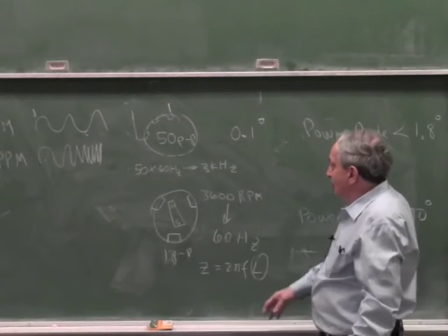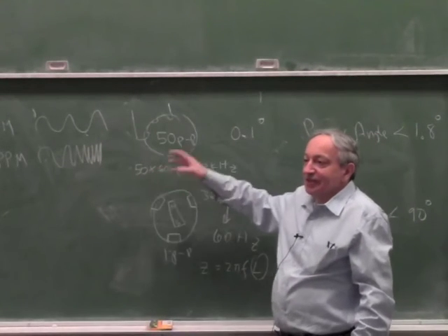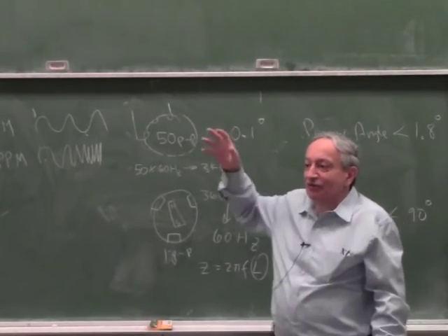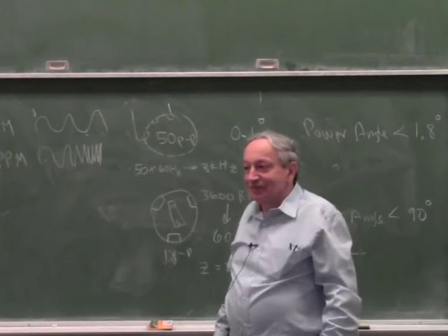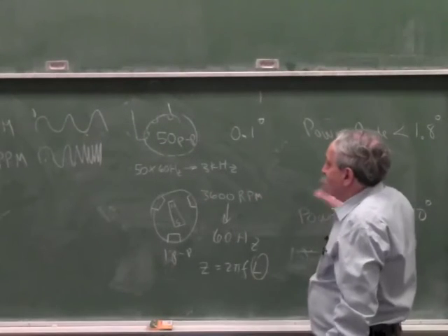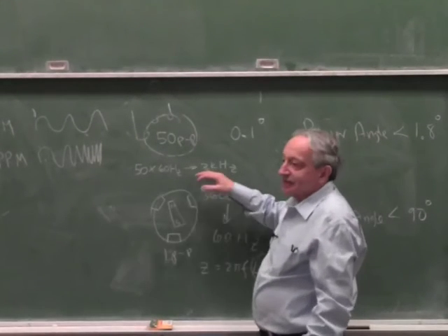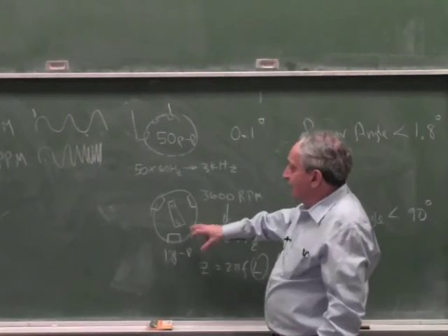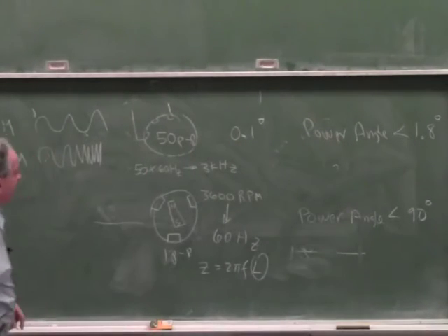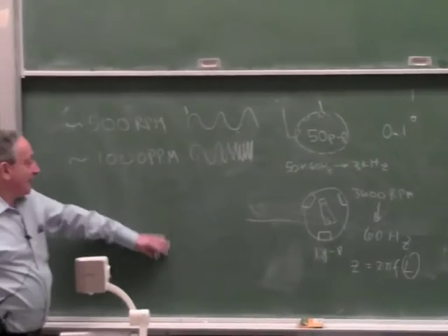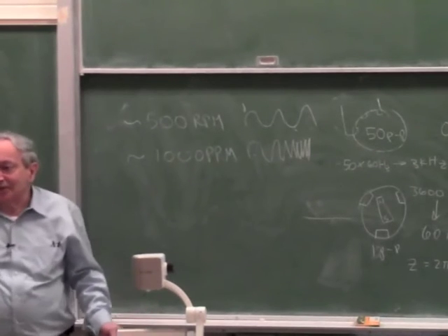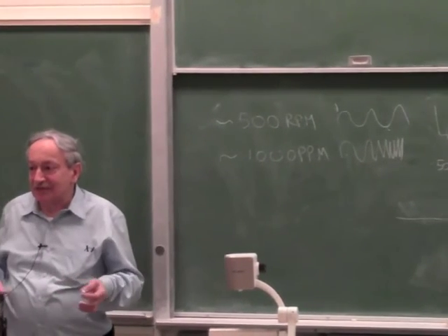If it's the same coil, you have to drive it at 50 times the frequency, the Z will be very high, you'll need kilovolts of voltage to drive it. So for many practical reasons, for power, angle, construction, inductance, this cannot run fast, this can run very fast. So this one can run up to, if needed, 100,000 RPM, usually limited mechanically by bearing